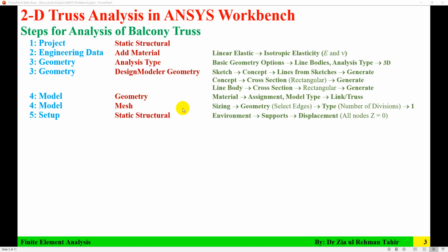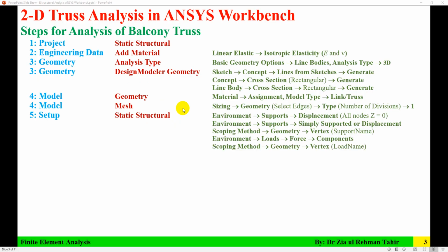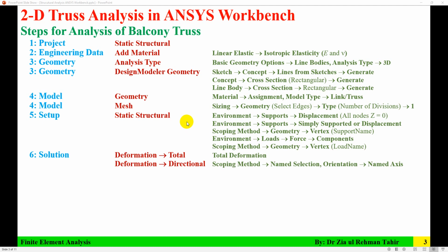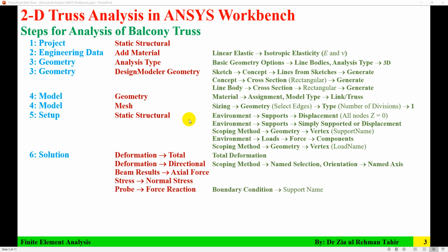In the boundary conditions, apply supports and then loads. Then in the solution, the requirements are deformation, axial force, stresses, and reaction forces, then solve, and then view the results for deformation, axial force, normal stress, and force reaction. So I am going to use all these steps to analyze this truss.